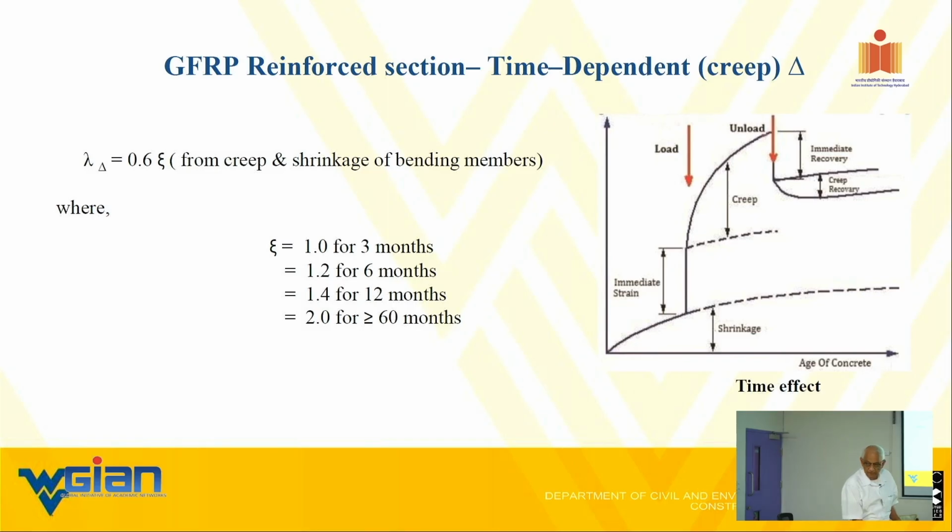In pre-stressed concrete also they will consider the creep coefficient when they are considering the Young's modulus. Right, which is, we call it a very low load rate. If a bullet hits, that is a high speed, so there the modulus is higher. In creep, the modulus is lower than the static modulus. So you are always comparing higher or lower with the static value. Okay, that gives you an idea. Now we can go back to, yes, sir.